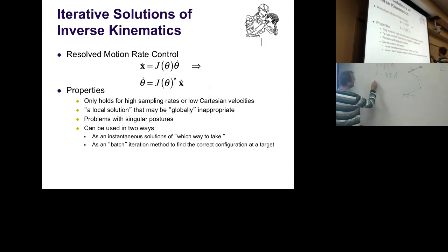discretization point of view. You can think of, I can make a little delta x, which is related to J of theta times a little delta theta, if you want to just do position steps. And all that I now omitted is that this here has to be divided by a delta t. And then we're back in velocity land. Okay, but the deltas have to be small, otherwise it's not going to work.